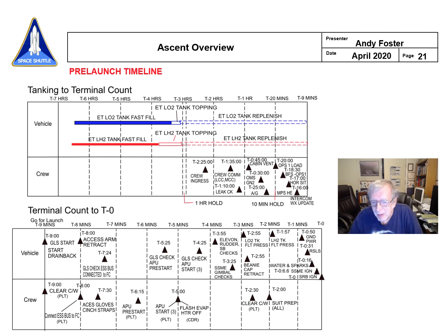And then at T minus 6.6 the main engines would come on, the computers would watch them, make sure they go to 90% thrust within 3 seconds, and if that occurred then it would continue with the count and light off the solids, I'm sorry, at T0. And then of course everything happens really fast from there. Once the solids light off, you're going flying, the explosive bolts release, and off you go.